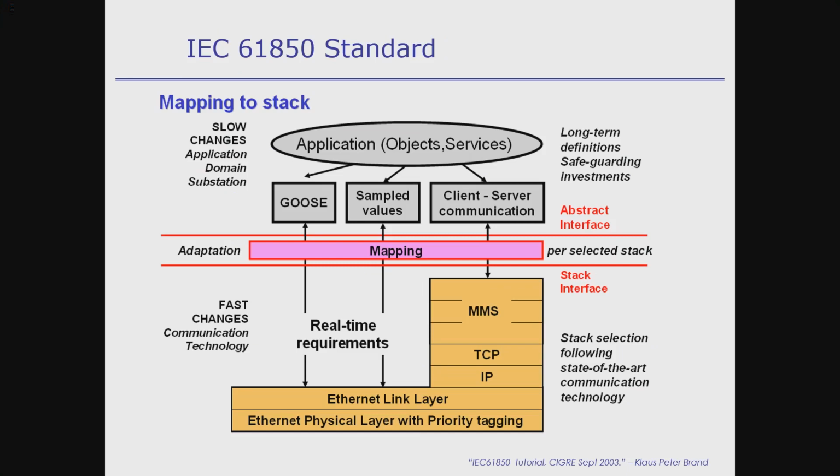So you can't use all the 7 layers, right? So what you have to do is you have to skip some layers. And so that's another type of service. And then there are GOOSE messages, which are generic object-oriented substation event. Any event in the substation, breaker opened, right? So that has to be communicated, right? Or you want an IED to open a breaker, that has to be communicated.